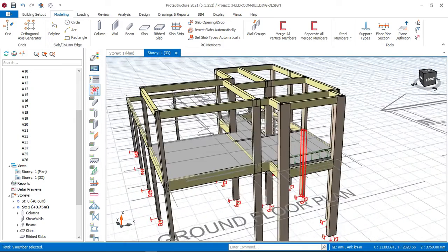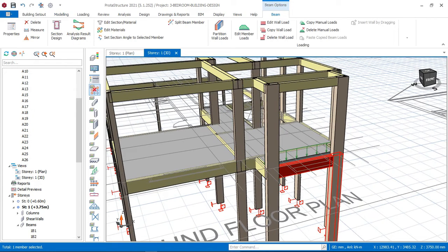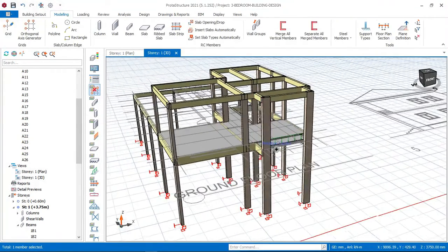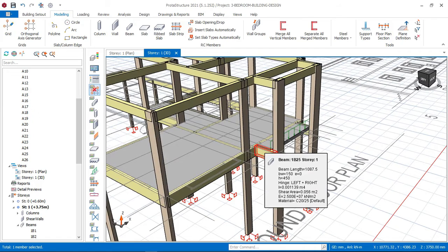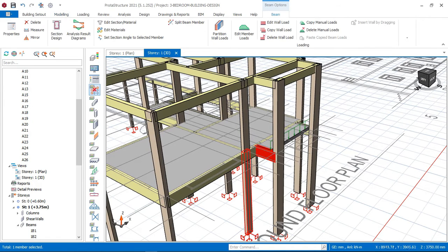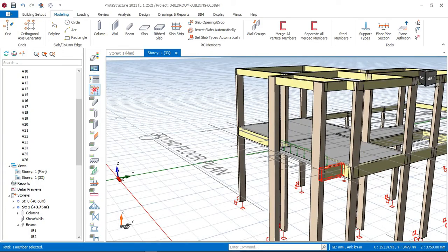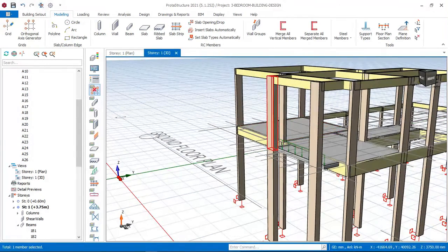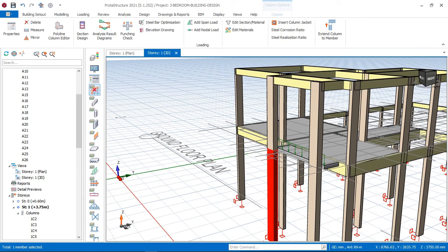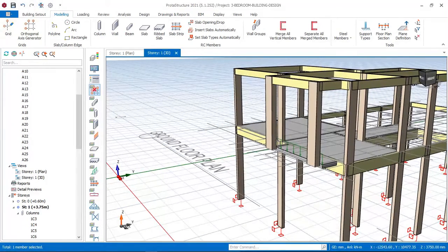So what I'll do right now, this place also does not have a beam crossing over it. So I'll just remove that beam right now. Okay, and then this place also doesn't have a beam crossing over it. So I'll take off this beam also, because it's just a cantilever slab that is showing there. So also on this place now, I'll remove this beam. Since I've removed all the beams right now, that means invariably this column is now a slender column. So I have to remove this right now, and remove this also, then apply this column to be a slender column.